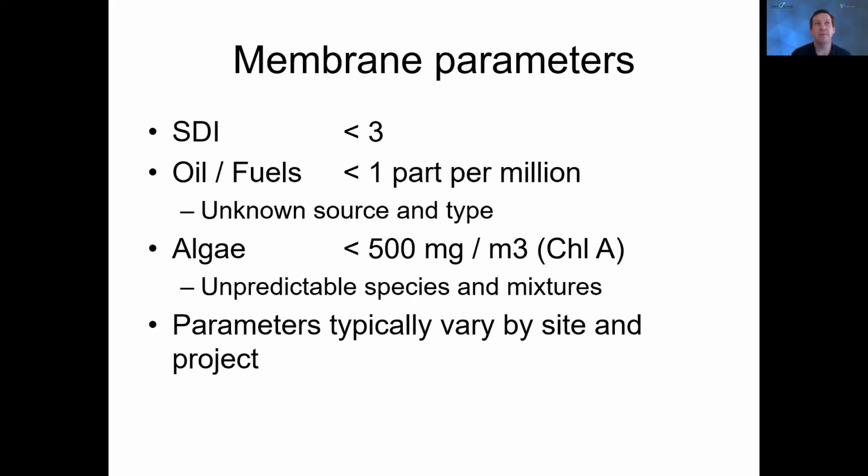I asked a couple of questions along the line as to what this means. And the reason I do this is that without some type of online instrument, regardless of the design of it, the only way to measure oil is manually grabbing a sample in a jar and taking that jar to a laboratory, analyzing the oil concentration in that jar, producing a response and saying, all right, we are at a half a part per million or 0.1 part per million, something like that.